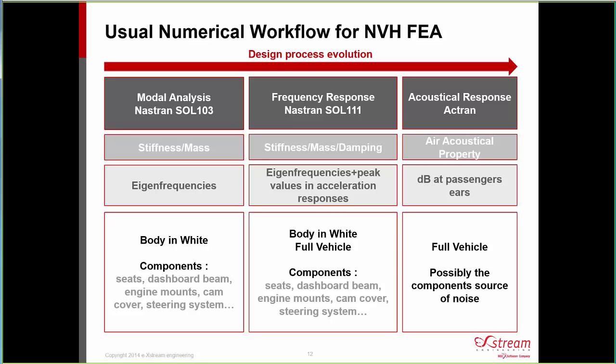And in the case of multiphase materials, it's really much more complicated than for metal, where an isotropic and homogeneous assumption was used for years and worked quite well. Then once all these vibration analyses are done, it's possible to do the acoustic response and to calculate the level of decibels at passenger ears.